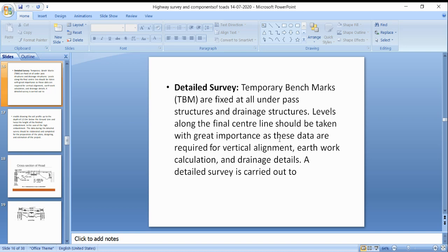Next, in the preliminary survey, we study ground levels, ground level conditions, and any important structures, so that we can deviate around them and give a better alternative. We have to see whether fences and other boundary lines are there, any commercial and industrial buildings along the route alignment, the position of quarries and any mines, rail crossings, and existing drainage particulars.